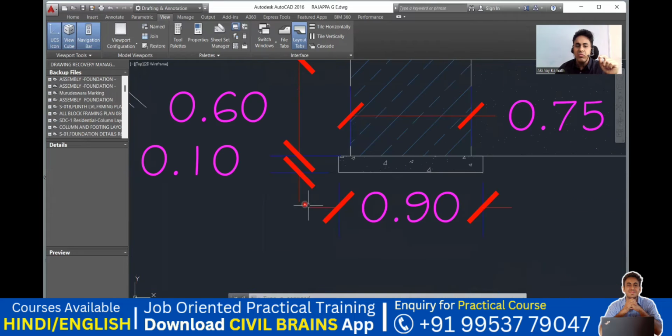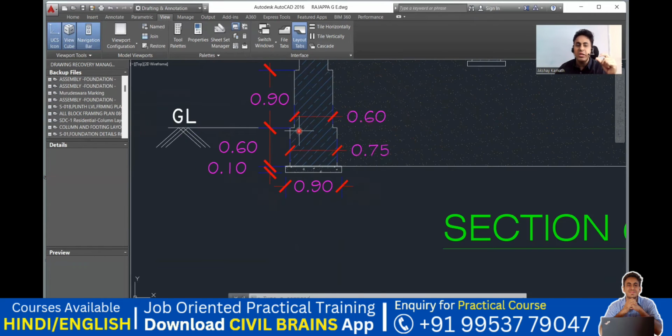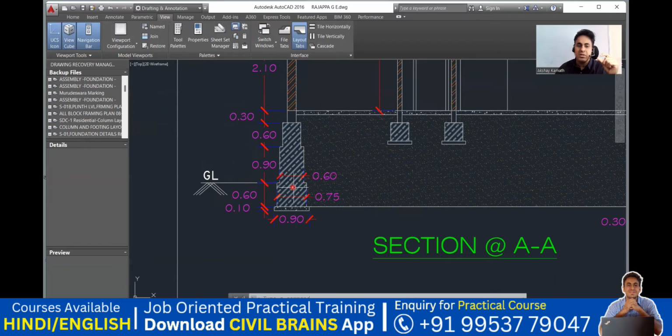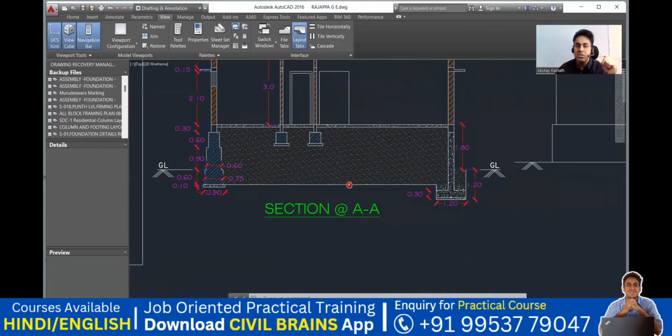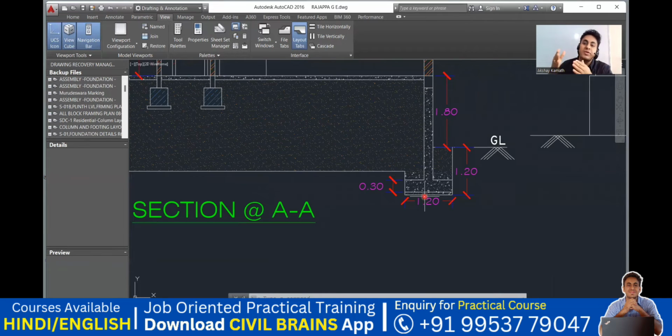And then this is the width of your PCC, which is 0.90, and the thickness of your PCC is 0.10, which is 100 mm. All of these are the stone work, the laterite masonry work you're supposed to do here. So this is the GL level. Got it? And these are the foundations you're supposed to do. For the foundation, you'll get a different structural drawing for the footing, the column and all. That we will take up in a live project, where I'm going to explain that.